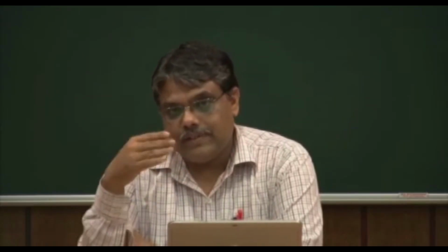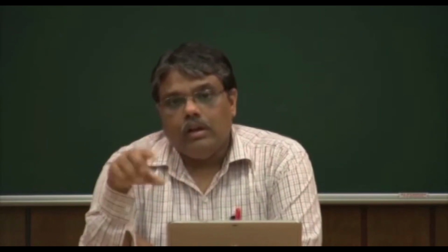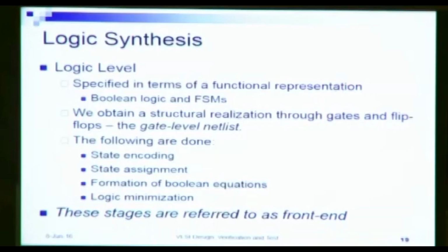So at the logic level, what do we have? We have the register transfer level design: the parallel register transfers at the output of the architectural synthesis step. We also have the controller, so we have the FSM of the controller.